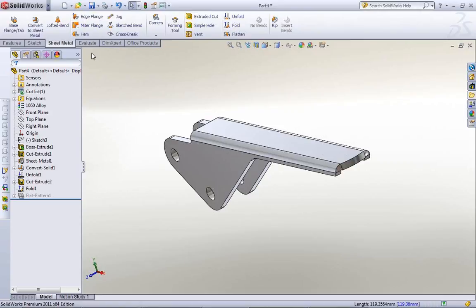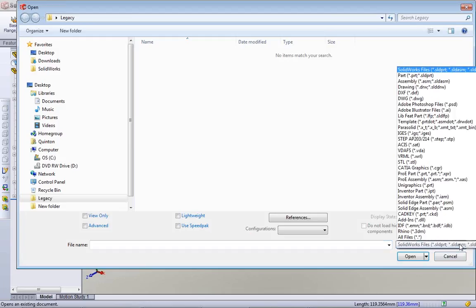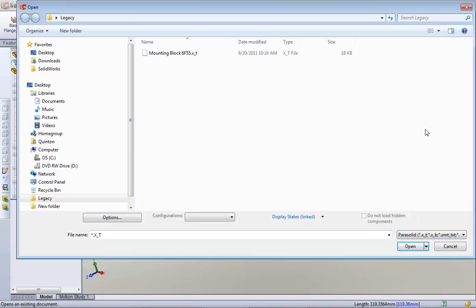Basically, let's jump over and take a look in SolidWorks again. Now, instead of opening these DXF or DWG 2D files, converting the entities to sketch entities, and then using those as the fundamentals of my part, I'm going to go ahead and bring in a file. And I've got a Parasolid. By the way, the Parasolid is one of the best ones for SolidWorks because they're built on the same kernel. SolidWorks is built in the background on the Parasolid kernel. Obviously, there's a lot of CAD packages like that, but